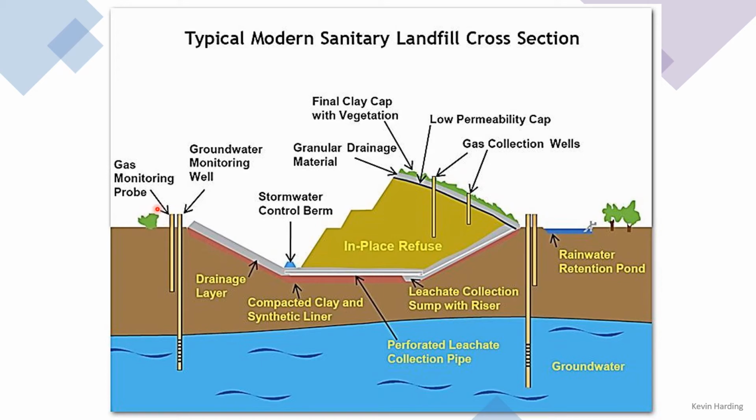Typically, let's just look at these poles on the right here, these pipes, these tubes. Because we often have groundwater in the area, so this isn't to scale, this could be a lot deeper than this. We want to make sure that nothing is leaking, so there'll be typically a groundwater monitoring well, so you drop a well so you can pull water samples out to check every now and again. There's no way of knowing if there's a leak or a break in this lining here, this red layer that we've got. If there's a leak, we'll never know unless we're monitoring the water.